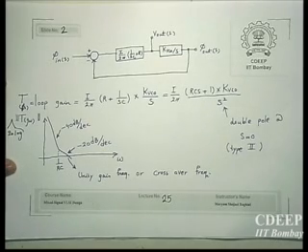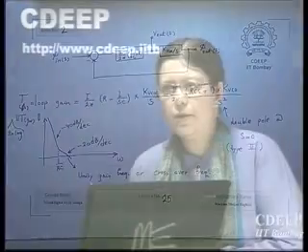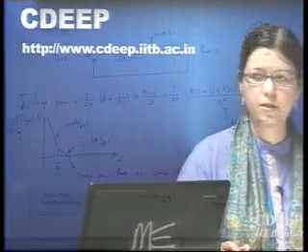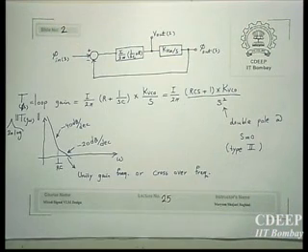So this is up to you how to choose this unity gain frequency, because eventually this crossover frequency of loop gain will determine your cutoff frequency of the whole feedback loop, which is the PLL. Eventually, bandwidth of the PLL is determined by the crossover frequency of the loop gain. So it is of the same order. And therefore, this is one of the parameters now for the design. You have 1 degree of freedom.